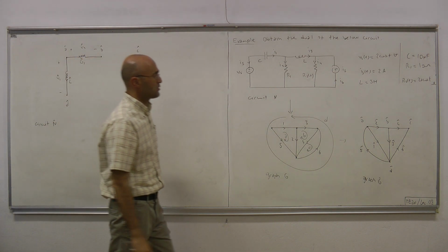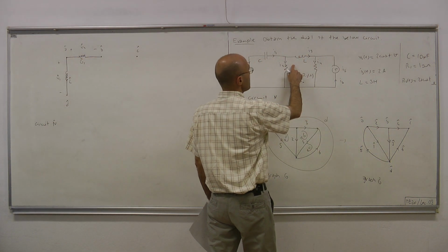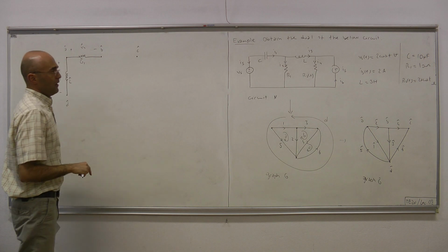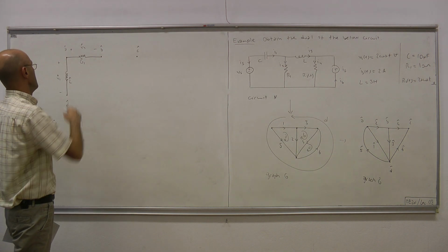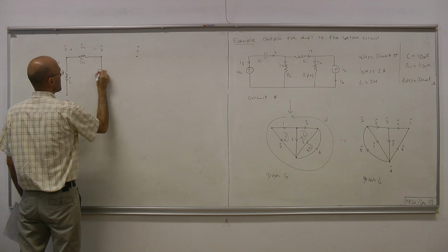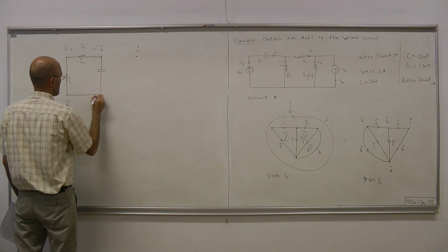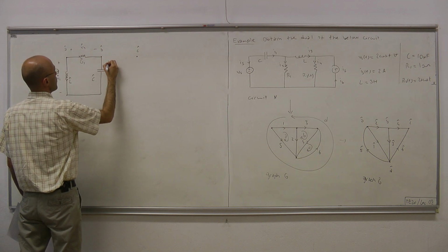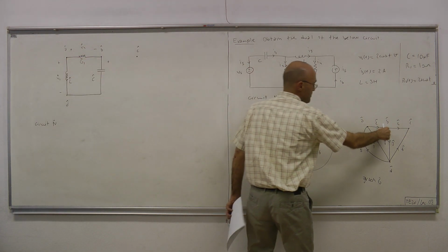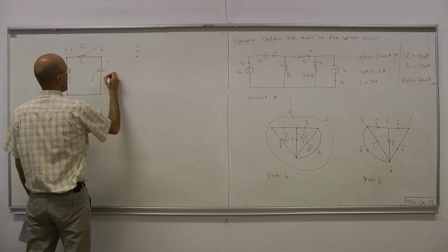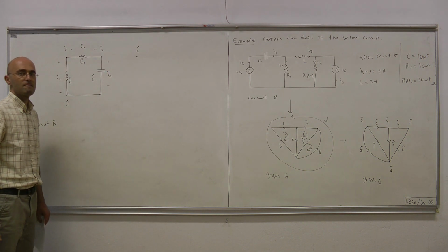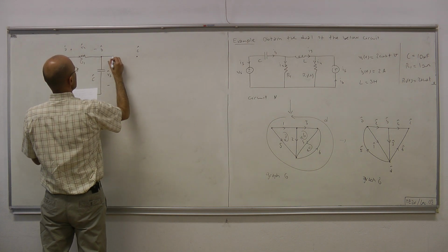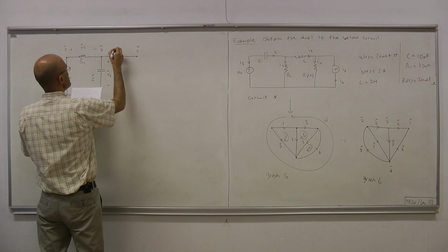Okay, third branch is from B to D, and the third branch here is an LTI inductor, therefore in the dual circuit it has to be an LTI capacitor. Okay. With capacitance C hat. And here the polarity is, this direction is from B hat to D hat, the polarity is plus minus V3 hat. Okay. And so, let me quickly place the remaining components. This is G2.